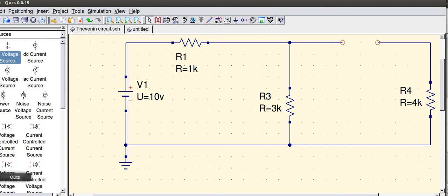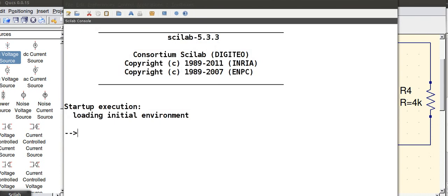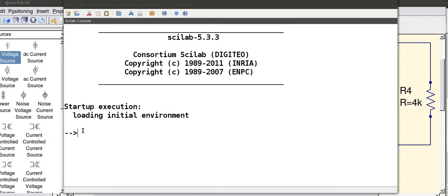If I want to solve that, then I'm going to pull up my calculator and figure that out. I'm just going to use the parallel resistance formula: 1 divided by 1000, or 1K, plus 1 divided by 3000, or 3K, and then I'm going to add that to my 4K resistor, or my 4000 ohm resistor. So I get a resistance back through the circuit equal to 4750.